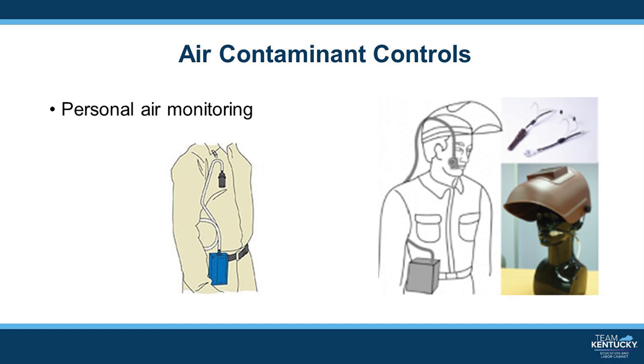From that, a Tygon plastic tube runs up the person's chest or back over their shoulder, and at the end of the tubing, a small air filter is attached to collect the sample of the welding fumes that might be in the air, which will identify and represent the amount of fumes that a worker breathes during the typical workday.